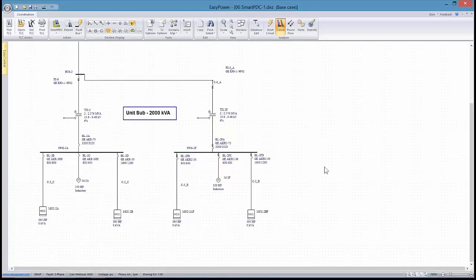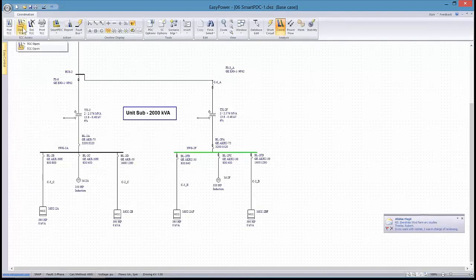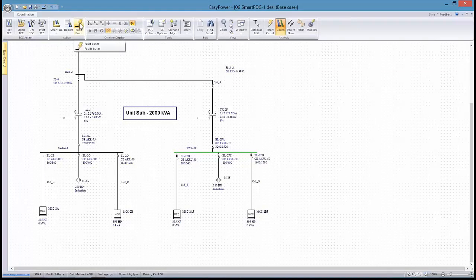All right, what we're talking about is a more complex system. Let's say I have this particular bus fault and we want to calculate arc flash energy and see where the resulting breakers will trip. I fault the buses. I've selected a specific bus, fault the buses.